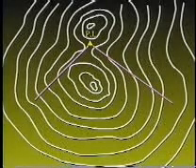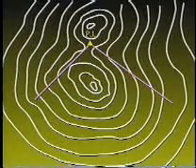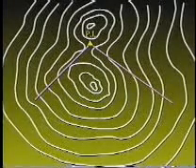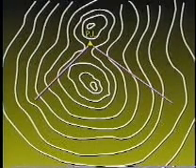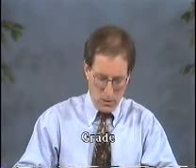In our example, the PI at the top of the hill in the saddle is placed along with the other PIs along the route so that changes in elevation between them meet design criteria. Elevations for the PIs are measured in the field or are obtained from a map or digital terrain model, and grades are calculated between PIs. Grades express the change in elevation along a line and are quantified as a percentage of slope. The relationship is change in elevation divided by length of the line.